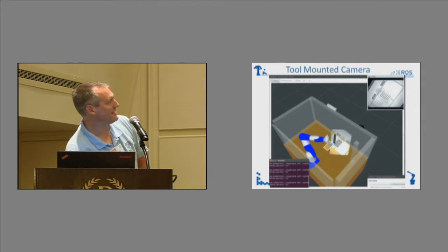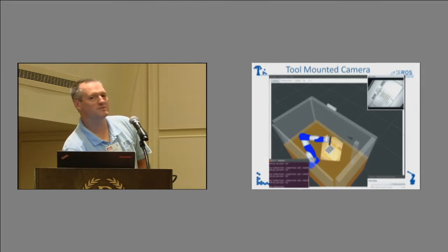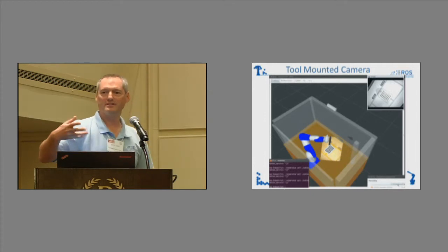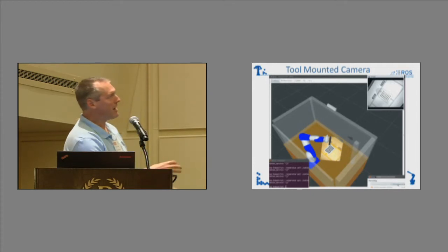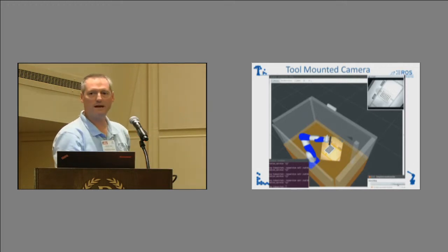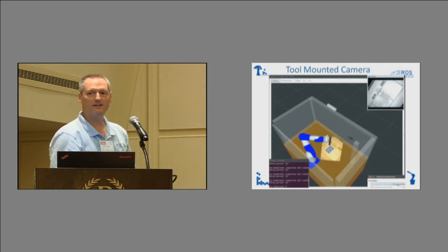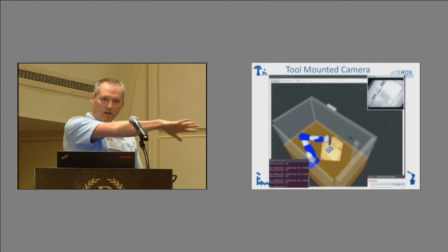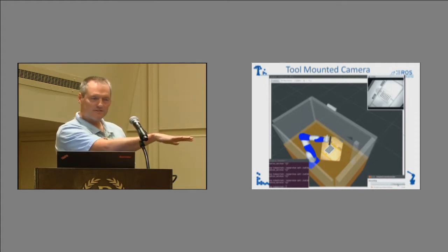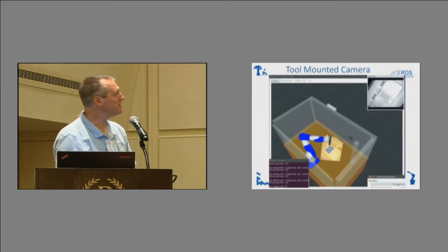So it's finished collecting the data, and now it's running the calibration. This is all just a live screenshot. What it's doing now is adjusting all the transforms by calling the services for the mutable joint state. And now they're all updated. You can see now that the camera is more or less where it was mounted on the robot. And the target, the planar grid of points, is no longer lying down inside the table, but is right side up. In fact, the 3D data from the ASUS sensor, that point cloud, is laying directly on top of it.